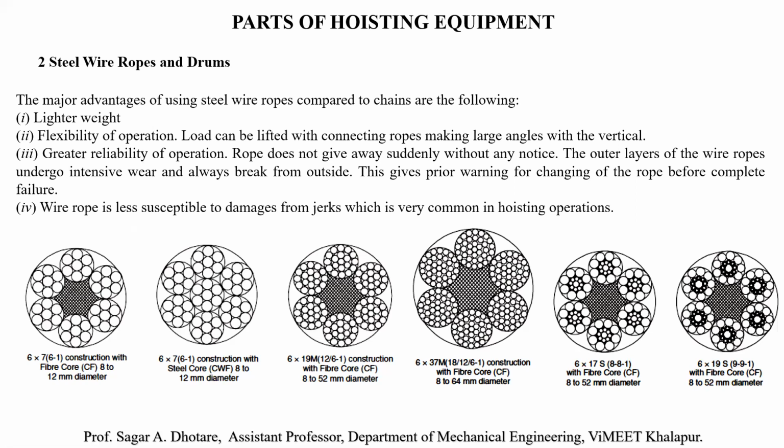The lifting capacity of a rope with galvanized wire can be about 10% lower due to the tempering effect of the hot zinc coating. If you galvanize the rope wire, the capacity gets lesser, 10% less if we are using tempered and hot zinc coated wire rope. So these are the two different aspects based on the type of wire rope we are using.